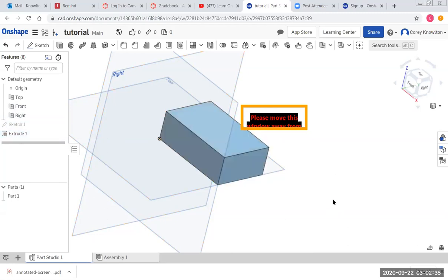Very good. So the steps that I had to take were, number 1, I selected the plane, and in my case, I selected the top plane. Number 2, I created a sketch. The third step was I dimensioned the sketch. The fourth thing I did was I check marked that I exited the sketch. So I'm going to write down exit sketch with a check mark.